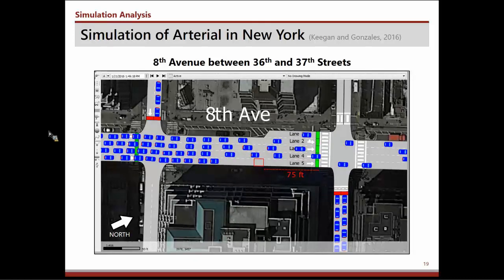And I guess we actually did also simulate the next intersection downstream so we could get the effective queue spillbacks in the case that mattered. And we loaded this model with traffic. In this screenshot, I guess there's only cars, but I'll show some videos in a moment. We loaded it with vehicle counts and heavy vehicle counts that were similar to what we identified in the videos of the street. We did try to simulate also pedestrian counts, but the number of pedestrians in Manhattan in this part were so great it overwhelmed the limit that our simulation package would track for pedestrian movements. And that's sort of a consequence of the heavy pedestrian volumes in New York.